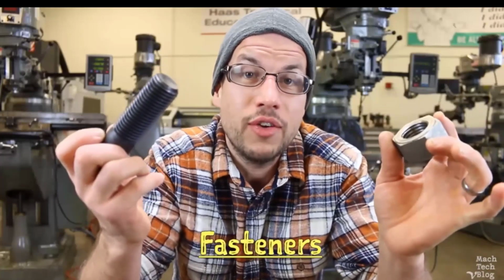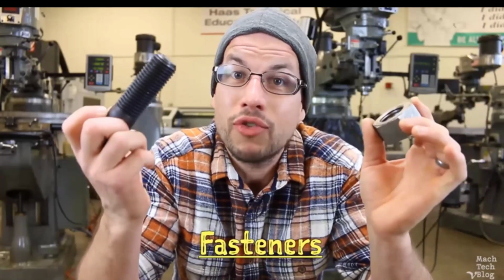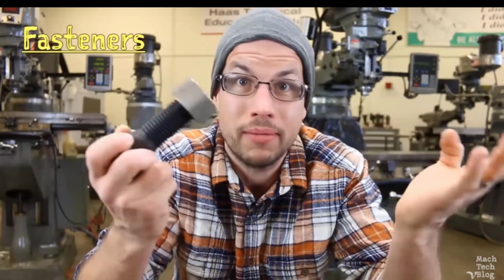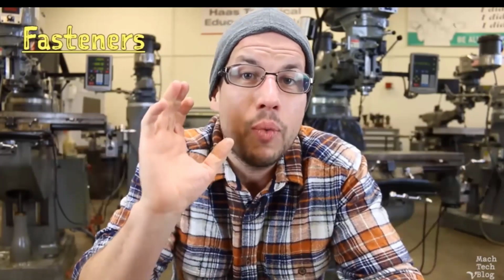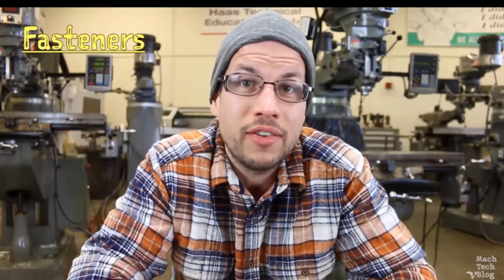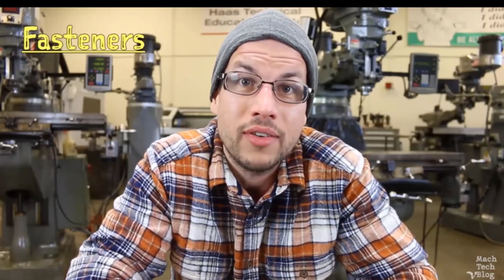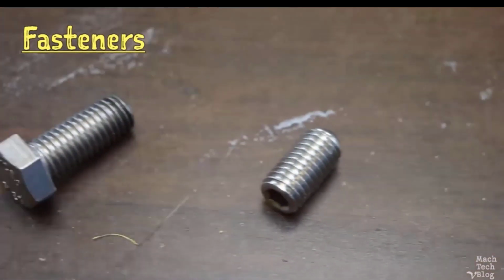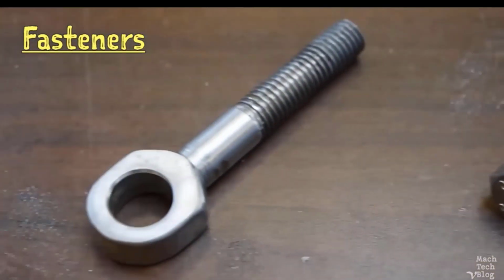They can be used for power transmission, precision measurement, making liquid-tight seals. But the most common use of screw threads is as fasteners, used to assemble components by driving an external thread into an internal thread and then wedging something between them. And there are a bewildering number of different threaded fasteners on the market for different applications. Socket head cap screws, button head screws, flat head screws, set screws, hex head bolts, swing bolts.